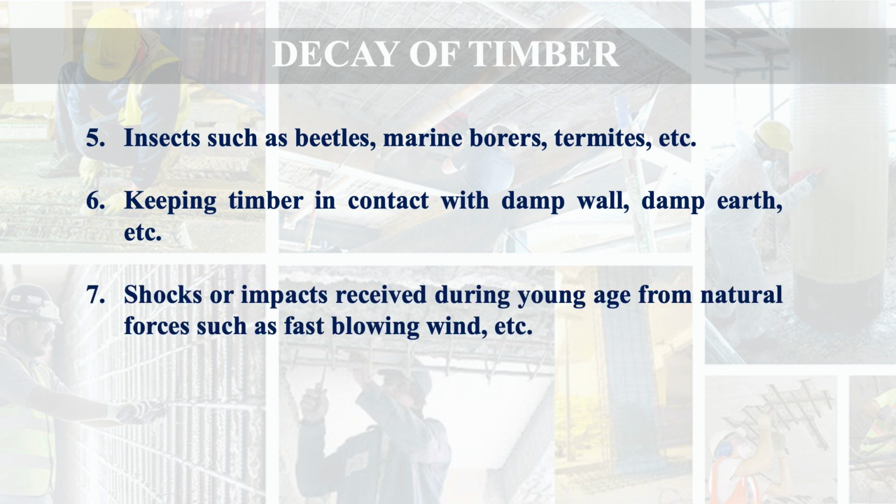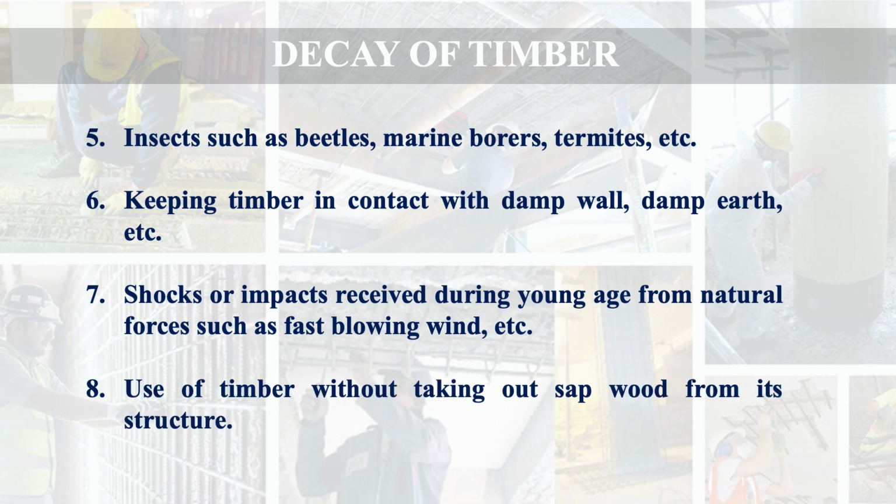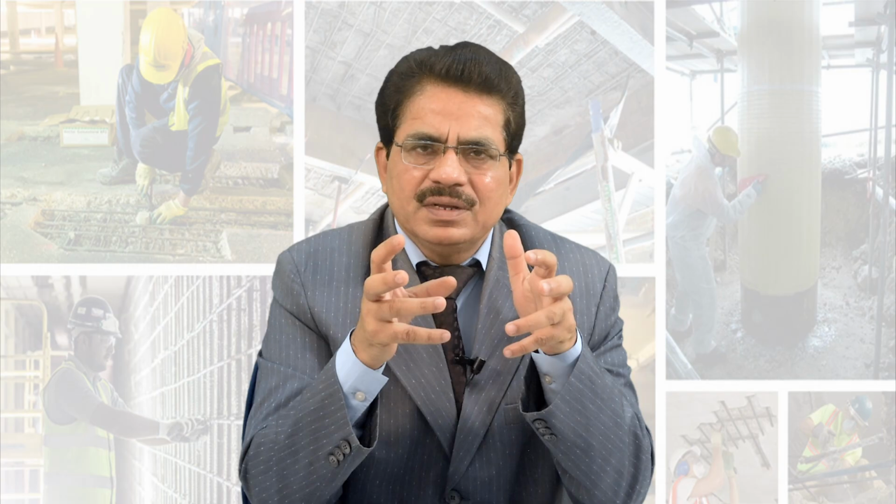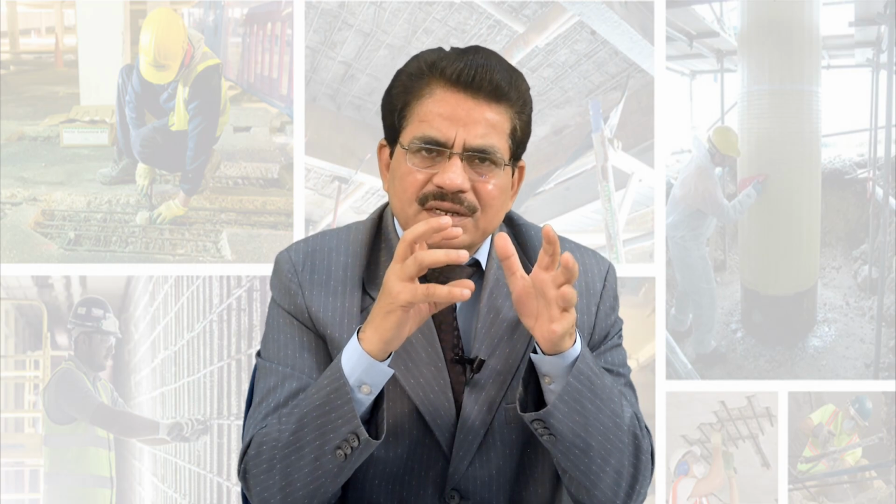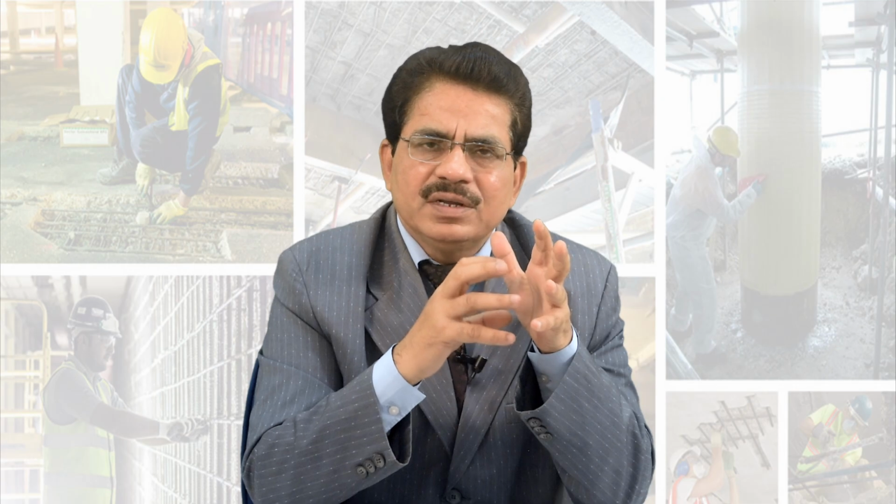Then shocks or impacts received during young age from natural forces such as fast blowing wind, etc. Then another reason may be use of timber without taking out sapwood from its structure. Any wood which still contains the sapwood, if you are using it, then certainly it is going to decay early.